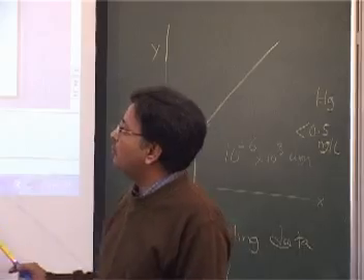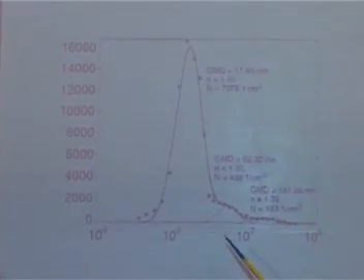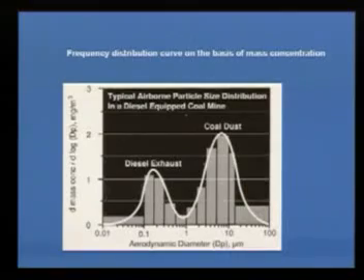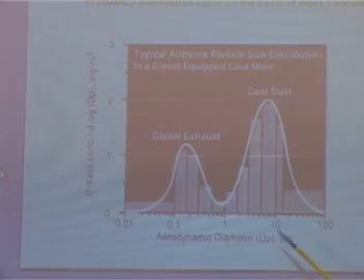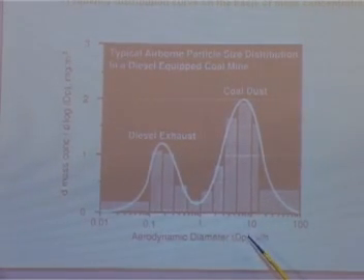So you can find that out, but what you see here is that the smaller particles are more in number. So you have to see the graph, whether you are talking about the mass or the number. And if you look at the mass, the distribution is entirely different. More mass comes from the larger size particles, and the numbers there are an almost insignificant number. So it depends on what you are using it for. Some medical doctors will prefer a number concentration rather than the mass concentration, but in environmental air pollution, we mostly need the mass concentration.